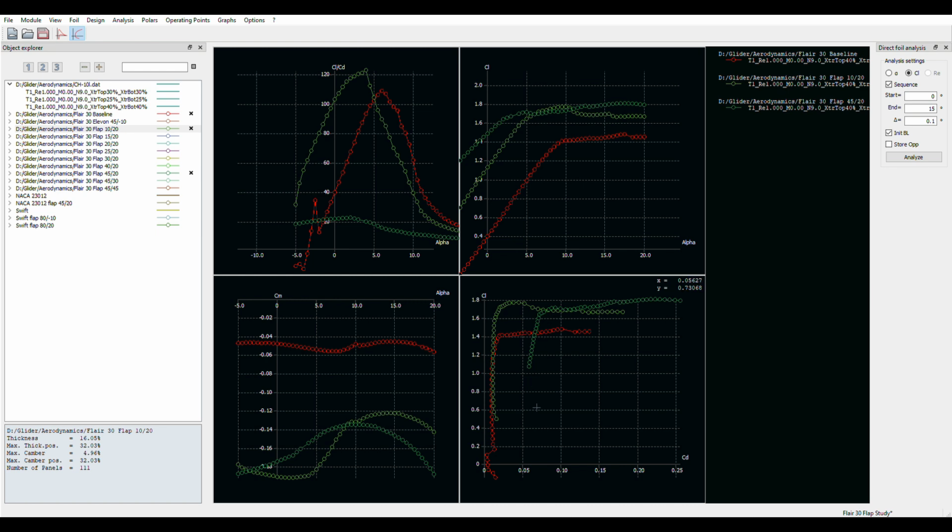So this is your classic physics problem of law of diminishing returns. Just because you made the flap bigger in chord doesn't mean you have better flap performance, doesn't mean you can fly slower. What it means in this case is you get a lousy L over D. So you put the flap down 20 degrees and it's only 10% of chord, you actually get a bump up in your L over D, and it occurs just at a lower angle of attack, somewhere around,